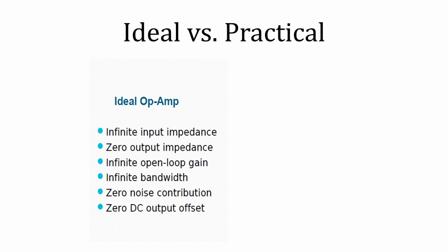The reason is its input impedance is very high. It will not draw current from its previous circuit. That is the meaning of high input impedance. And what is the meaning of zero output impedance? Just the reverse of it. If we connect the output of the OpAmp,